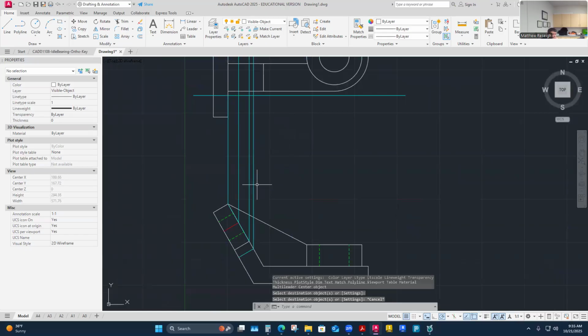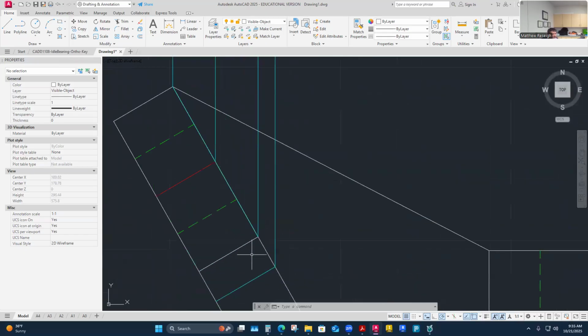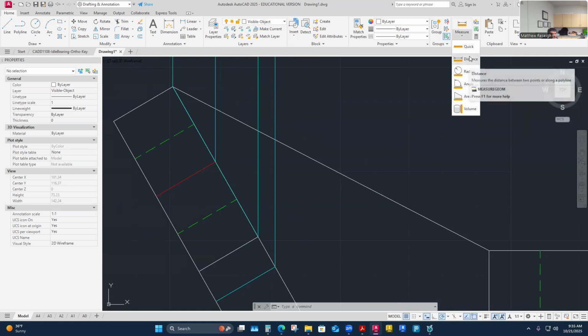So really what I have is that this ellipse is going to be in this view. I see that it's 25, or sorry, 50 millimeters all the way across. Well, when I project that up, it doesn't really measure that. It's foreshortened when I'm looking at it in the top view.